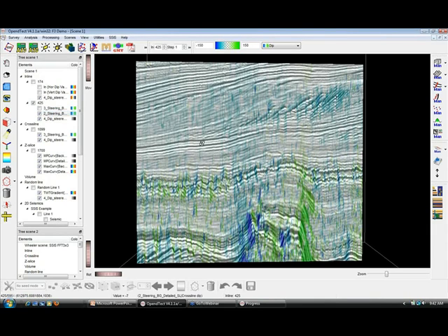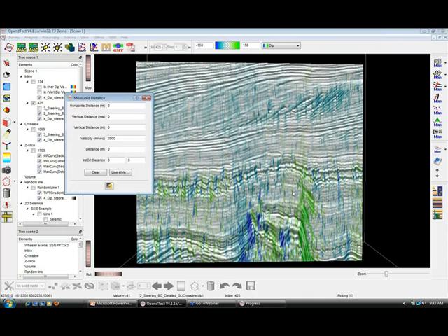I again put it in a semi-transparent layer on top of the seismic. Now it's not very useful because you just see the dips and you see the faulting on the section, but I always look at the dip attribute as such on the section as quality control. I want to see if the noise is really out there and if the dips really represent my correct dips. Keep your eyes fixed to here. If I go over the volume, I see actually the dip value. This is a cross-line dip displayed on the inline, so the dip from one cross-line to another. I see the value down there, and I can potentially verify if that's the correct dip by the measurement tool here.